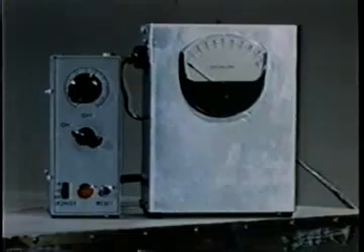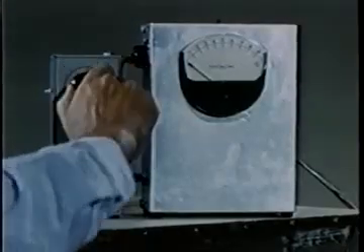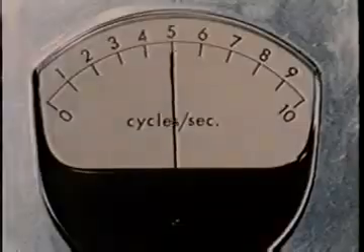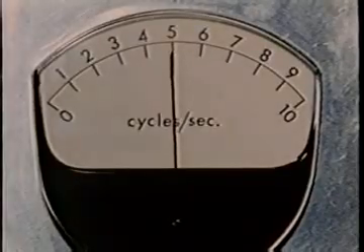In order to find the frequency response of amplification, we put in sinusoidal disturbances which we can control. We start the wave maker oscillating at 5 cycles per second at 0 airspeed, and watch the waves as they travel away from the wave maker. With the tunnel running but below critical airspeed, we don't notice much change in wave damping. As we increase the airspeed and pass critical speed, we see the waves grow.